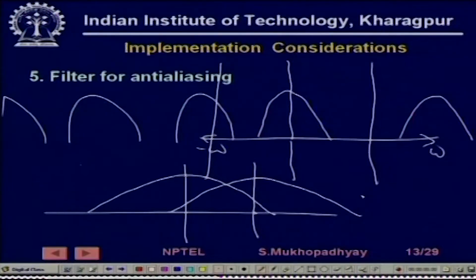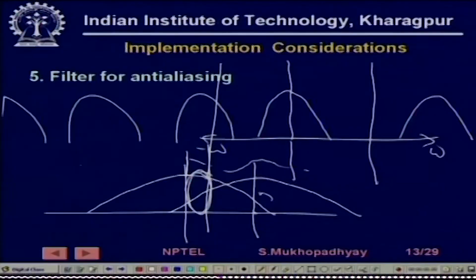So, what will happen is that effectively once these two lobes are summed, the frequency spectrum of the digital signal will look something like this. This is a very important part of the signal: for control, the low frequency part is generally very important. You see that the high frequency part of the signal, which was not so important for control, has folded back onto the low frequency part and is now affecting it. I am telling this very briefly.